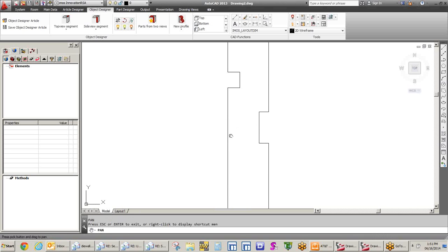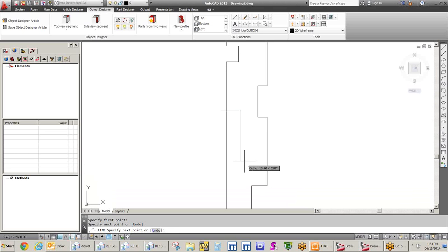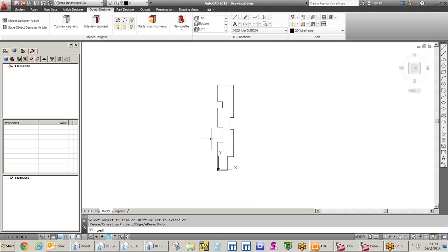Maybe I want to be able to say, hey, I want a line to go across the stud that is going to be, you know, this height by, you know, 8 inches and back out. I could use the trim features to be able to work with this. And now again we'll p-edit the polyline and tell this to join, so that now we have one single object here as a polyline that we'll use.